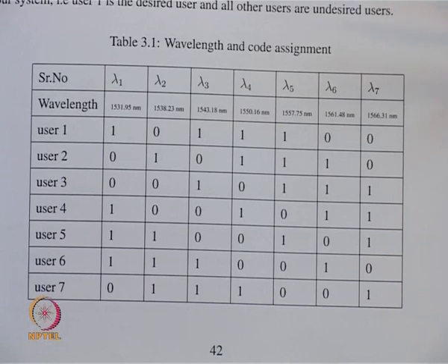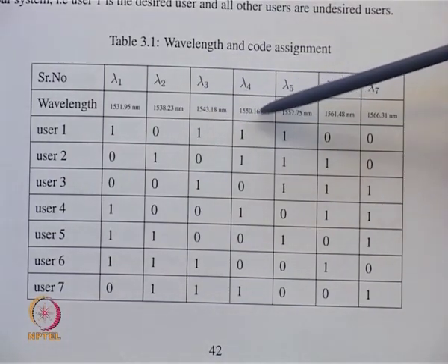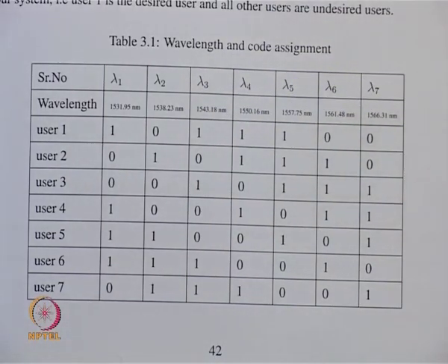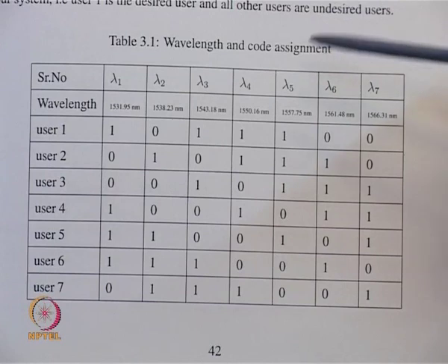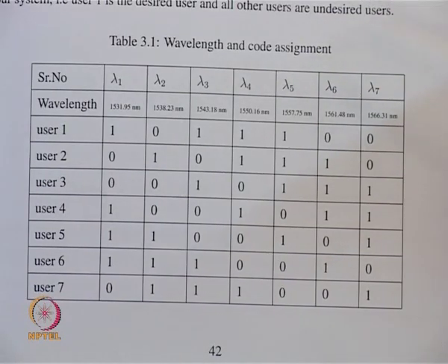7. Each wavelength, lambda 1, lambda 2 to lambda 7, can be obtained by connecting a broadband source to a series of respective gratings which are reflected, and the output is taken through optical circulators. So for a system with code length of 7, the table gives the signal encoded for user 1 to user 7.